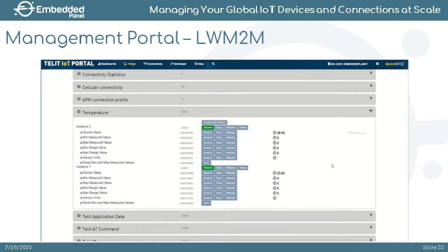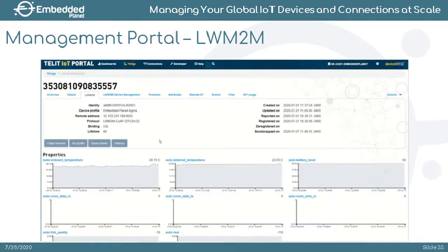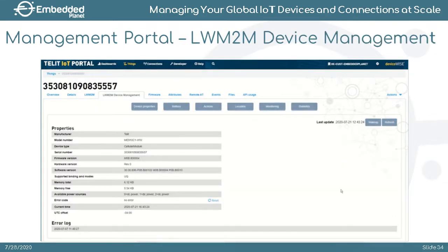And then also there are created objects for temperature. So there's a standard object of 3303 for temperature. And if we sit here for a second, we should see a new piece of data come in for the onboard sensor, which is instance 0. There you go. So it live updates, gives you a nice interface into the data under the hood.